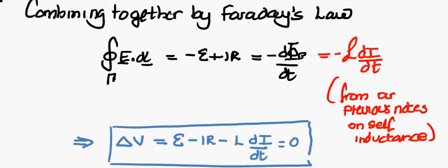For a perfect conductor, we're only going to consider the magnetic flux associated with the coil inductor, single coil inductor. So here we have our integrand around our loop in the counterclockwise direction, and then this must equal the magnetic flux that goes through. So we can relate that to our inductor, and so our voltage drop across our entire circuit must be our external source of EMF, the voltage drop associated with our resistor, and then our inductance term, and this is equal to 0.